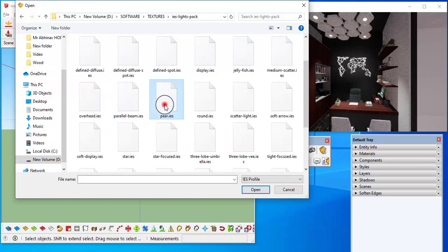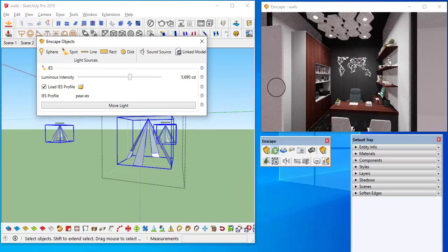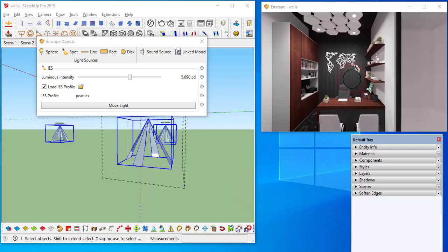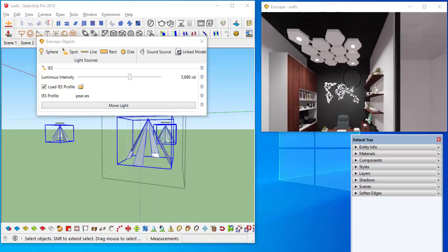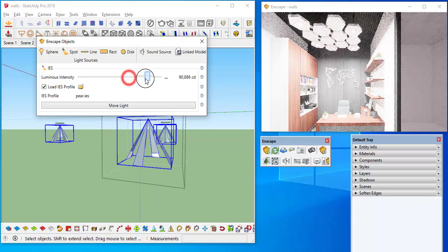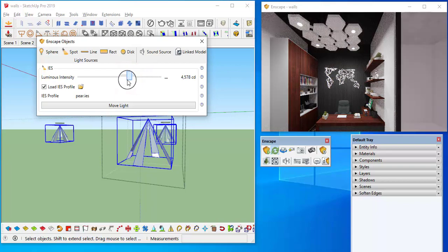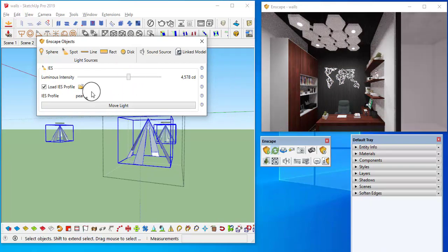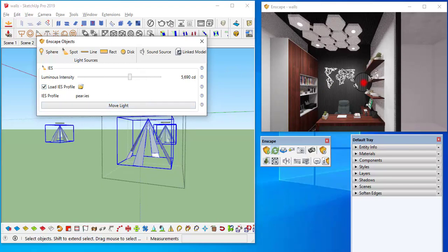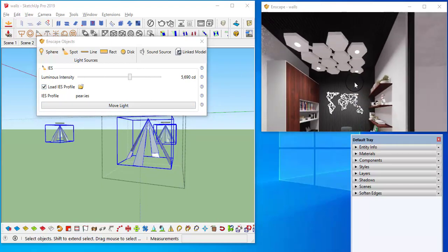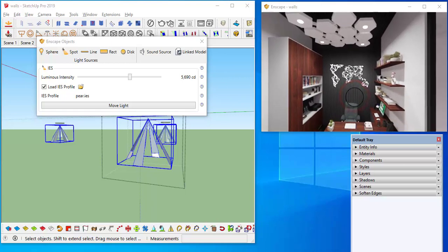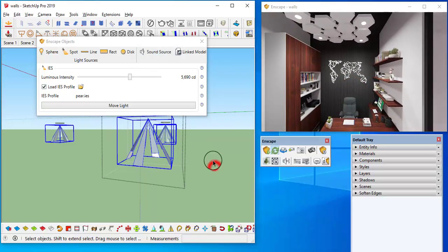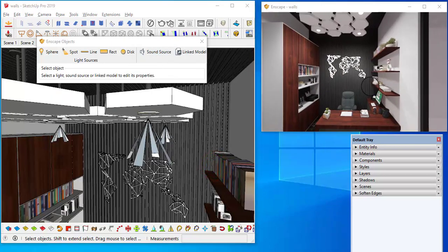Here, this is actually good for me, for my taste. See, this is how I want. If you adjust the brightness, the same thing, but the cone angle, everything will be in that IES profile. Okay, one by one we will adjust the material. This is the lighting I want, that's it.